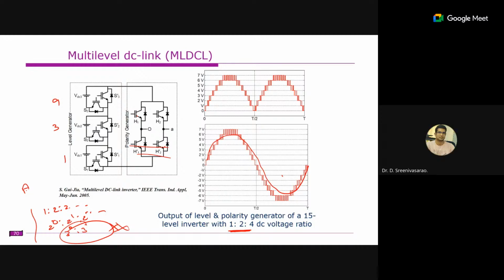So depending on the voltage waveform, we can say whether the harmonics are reduced or not. It does not depend on the switches. Because of the switching, only the current harmonics will be distorted. There are two: one is voltage distortion and the other is current distortion. Because of this switching, only the current distortion will happen at our grid. The voltage distortion depends on your application.